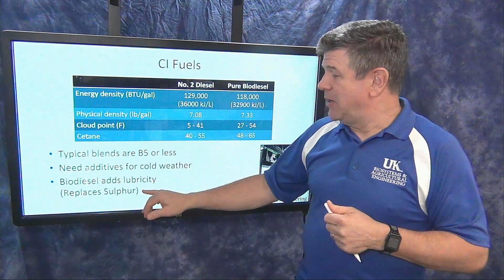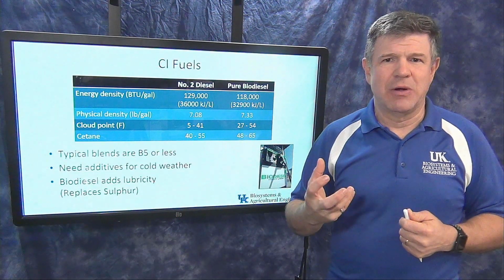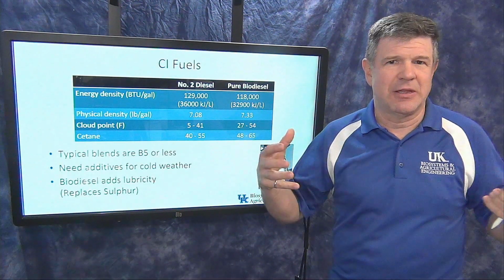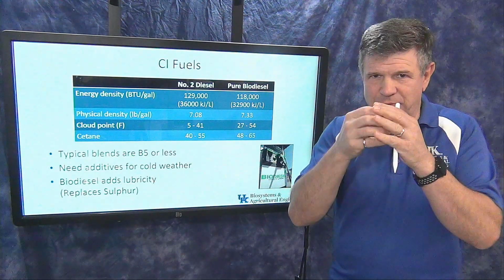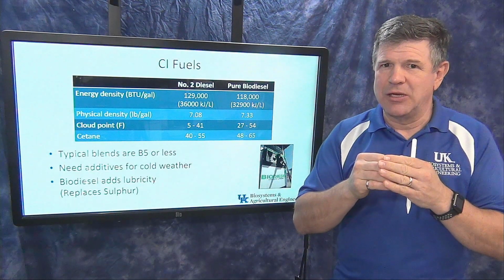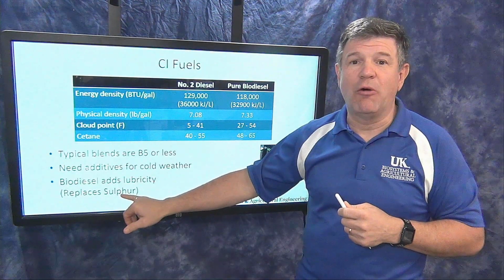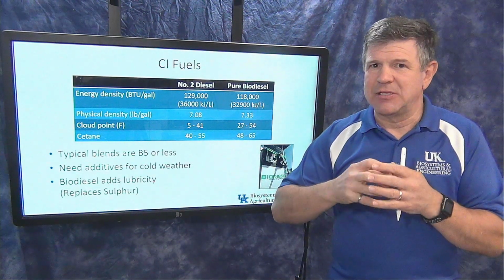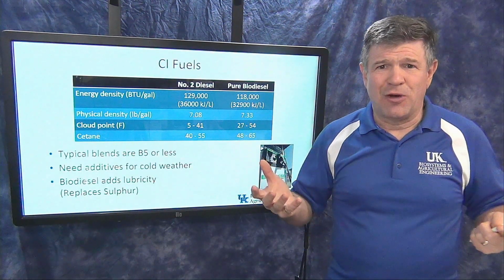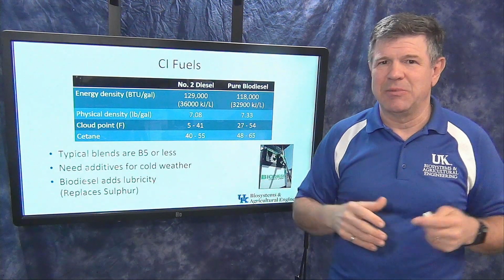But one of the things that biodiesel does for us, and I'll mention this in terms of diesel supplies, is it adds lubricity, it adds lubrication. As that fuel has to go through the engine, through an injector pump and stuff like that, there are a lot of moving parts and very tight tolerances in those injection pumps. So I've got to have some type of lubrication in there. If you go back a number of years, our diesel supply had a lot of sulfur in it. And that sulfur is what gave us that lubricity for the fuel injectors, for the fuel pump, and so forth. Well, sulfur is not good to be burning and blowing out into the atmosphere. It becomes sulfur dioxide. It becomes nasty stuff.